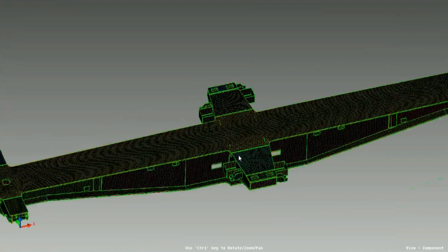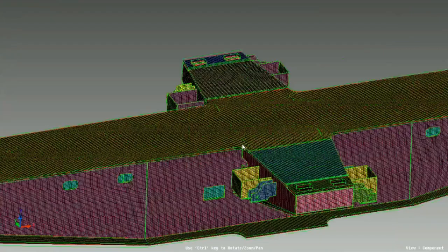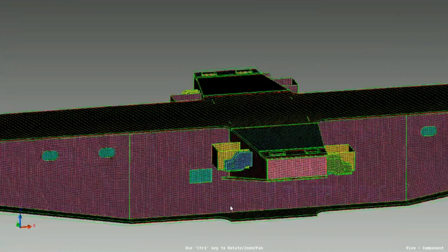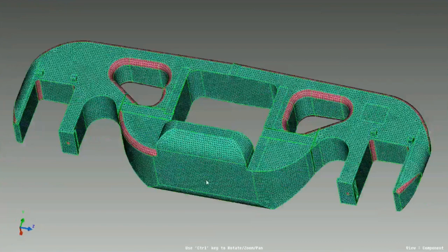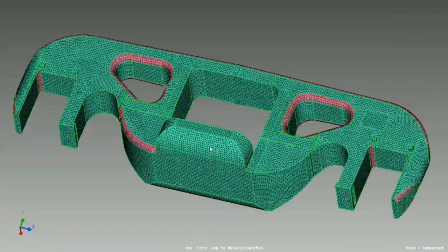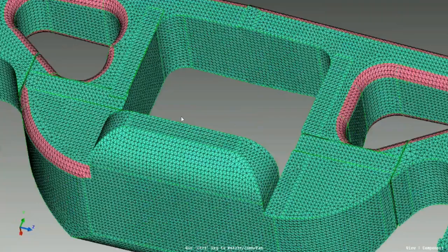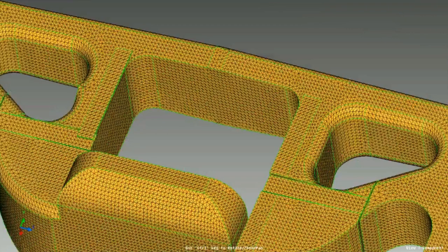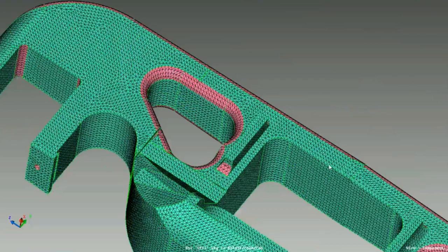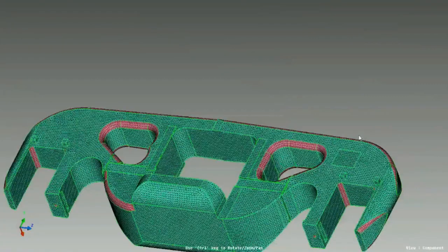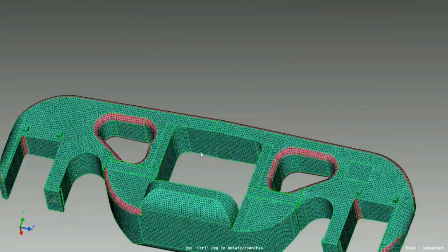And so this is the sheet metal midplane, automatic midplane meshing. Similarly, we can also mesh a casting component like you see here. We can specify a different template, and based on that Meshworks will automatically create a tetra mesh model, and also it will identify features such as fillets and some walls. One advantage of using Meshworks is that once the model is meshed, the model becomes automatically parametric, and associativity is maintained between the mesh and the CAD.